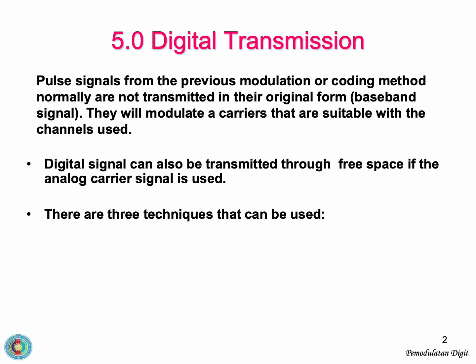Before we dive into the how, let's address the fundamental why. Why do we modulate digital signals? Raw digital pulses, what we call baseband signals, are generally not transmitted in their original form. Think of them as raw data that needs a suitable vehicle or carrier to travel across a given channel. This modulation process makes digital signals suitable for transmission through free space, using an analog carrier.